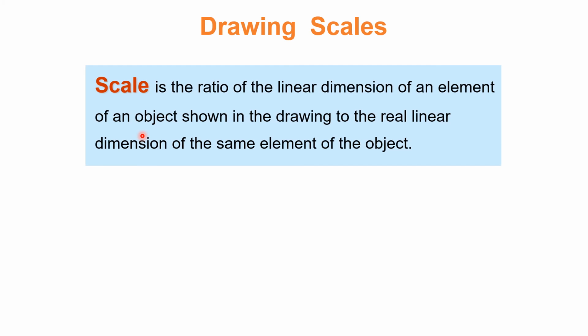Drawing scales, that is a very important topic, used most of the time in drawings. Scale is the ratio of the linear dimension of an element of an object shown in the drawing to the real linear dimension of the same element of the object. What it means, like our buildings,